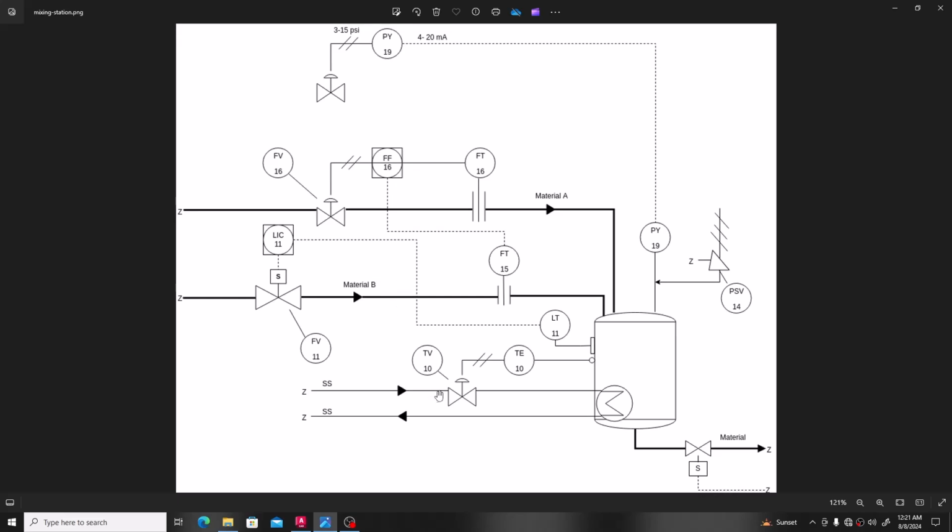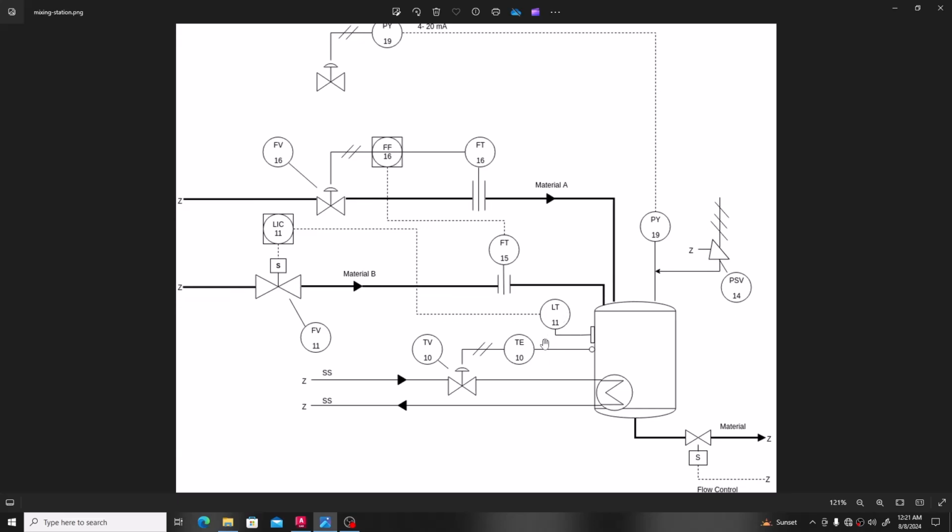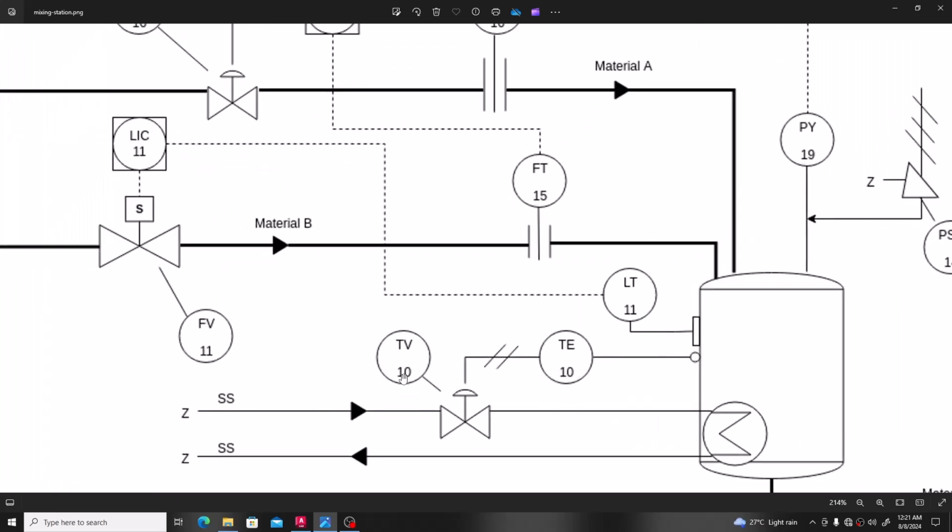Okay, anyways, let's try to create this P&ID drawing, making use of blocks, attributes, etc. Using the simplest method and the most advanced and efficient method, we will be creating blocks with attributes for these circles. I can see that all of the circles are the same, which includes two texts, one at the top and the other at the bottom. Right at the top, you have an alphabet, and right at the bottom, you have a number.